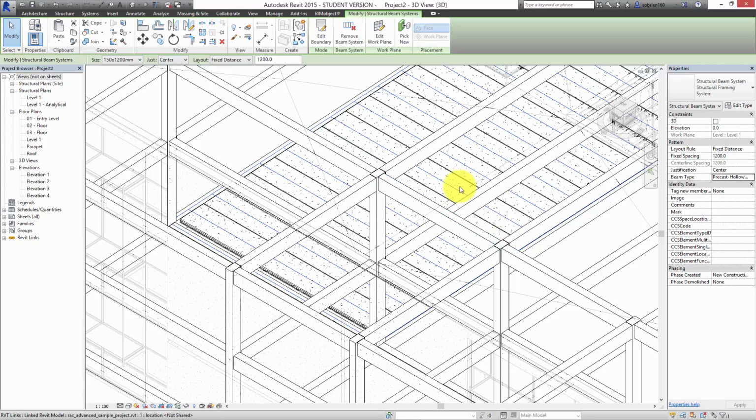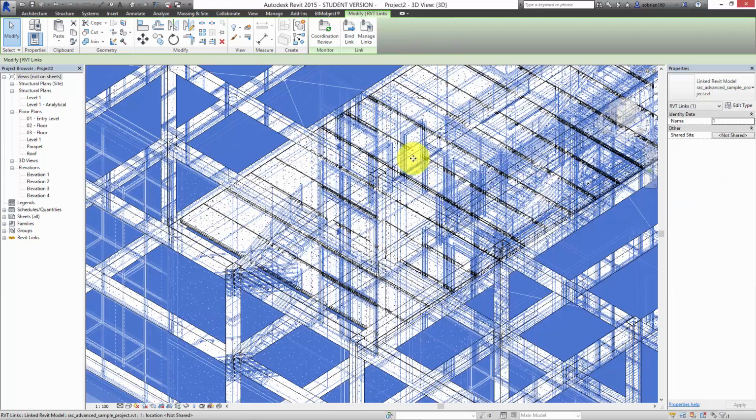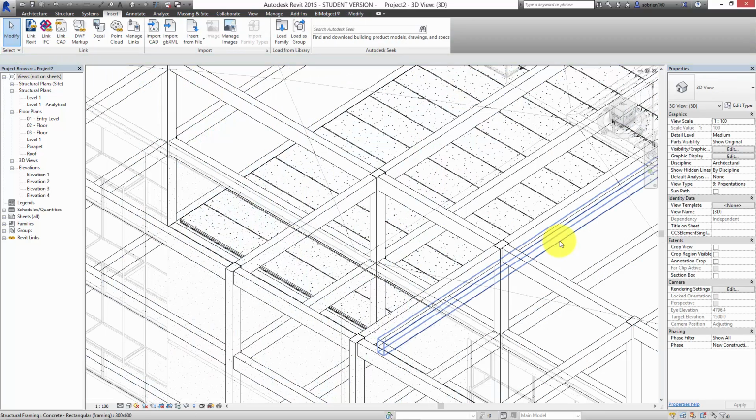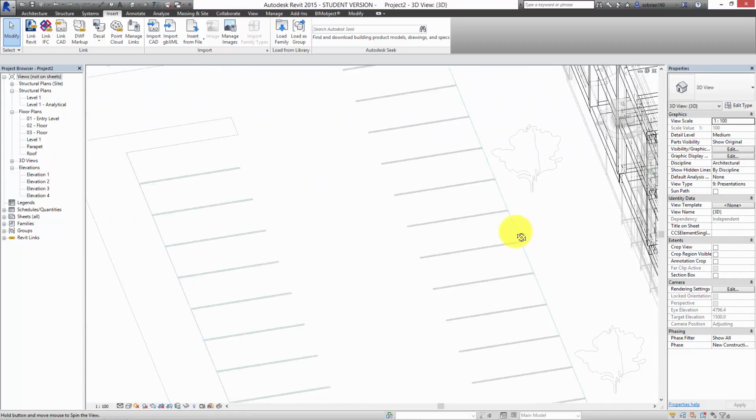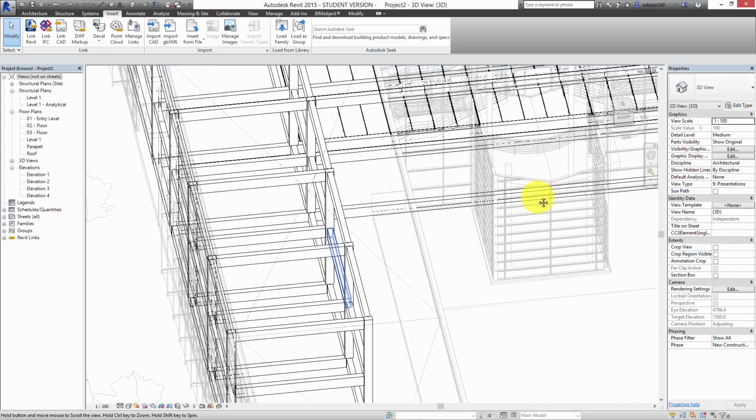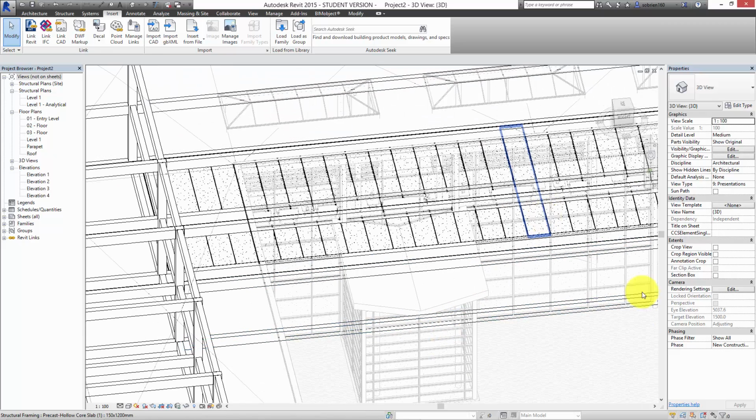So you could go around and fill in the slab system piece by piece. I wouldn't do the entire building at once. I would define your supporting beams and make a slab system in between individual elements of it rather than do the entire building at once, because it just gets out of hand. Also, it's unlikely you can get 60-meter long precast slabs anyway.